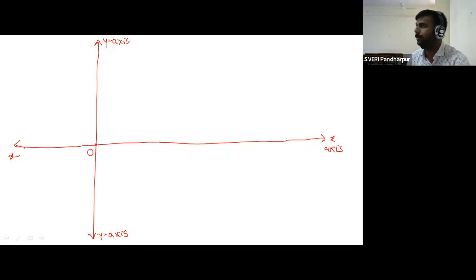So this is the first step: you have to draw the horizontal axis and vertical axis. Then we have to select the scale. Write this scale at the top right corner of the notebook. See, scale: 1 centimeter is equal to 10 Newton per mm square. Write down at the top right side corner 1 centimeter is equal to 10 Newton per mm square.